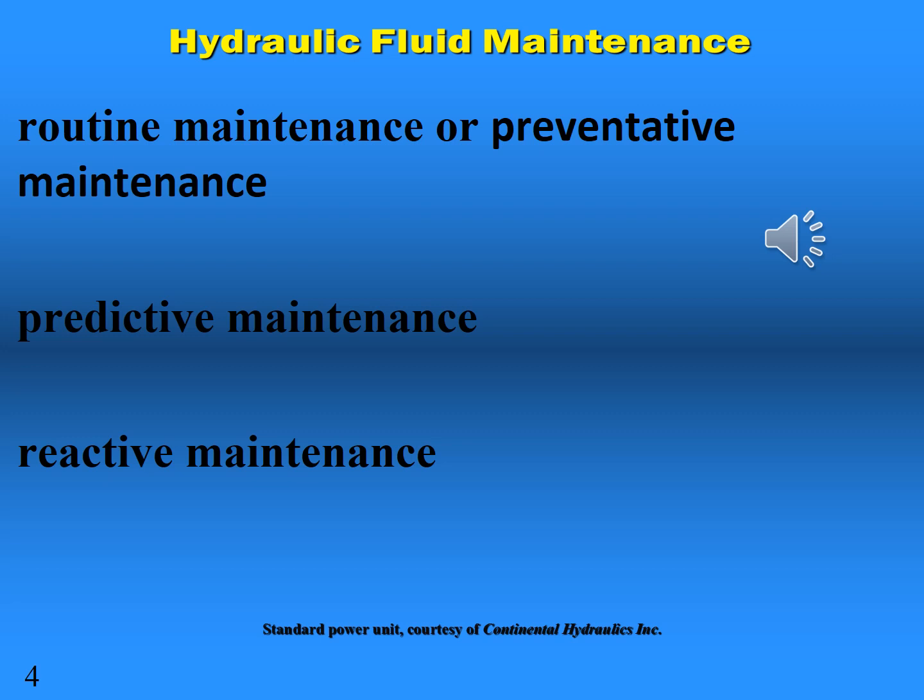There are many ways to identify the type of maintenance a company practices, but no matter what it is called, it will generally fall into one of the names here. Regular service falls under a plan called routine or preventative maintenance. There is a form of maintenance plan called predictive maintenance, which practices the repair or replacing of key components before they wear out, thus, in theory, eliminating a breakdown before it happens. Some companies, unfortunately, do not prioritize preventative maintenance and suffer a pattern of abuse called reactive maintenance.